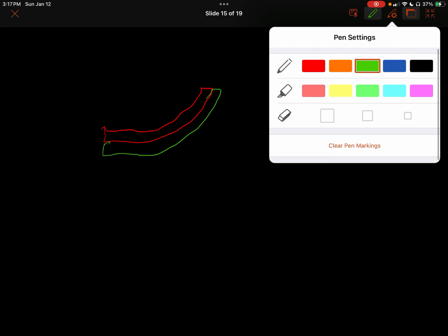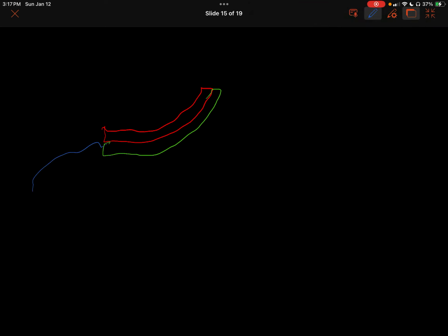And so what was originally flat, one side's going to expand more than the other, and it will cause that bimetallic strip to bend. And when it bends like this, we still have the wire coming in one side, but it will break contact from the output side, and so now the current drops.